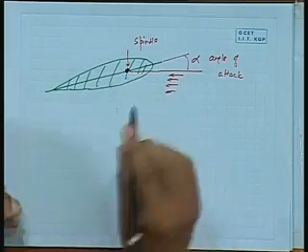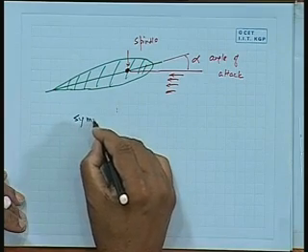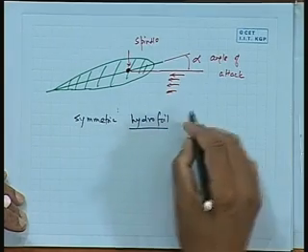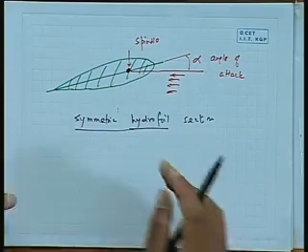You will have a rudder spindle here. Of course, this is a symmetric aerofoil section. Let us use the word hydrofoil. It is symmetric mostly because you want it to have the same performance on both sides, not like an airplane where you have an unsymmetric aerofoil, because you want the plane to only go up, not down. Similarly, propeller, you only want force in one direction mostly, therefore it is not symmetric. But in this case it is always symmetric because either turning port or starboard you want equal kind of forces.